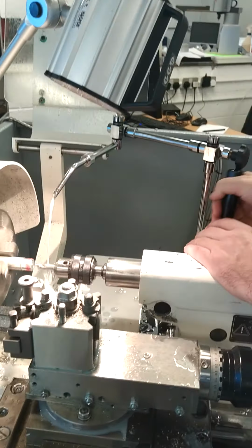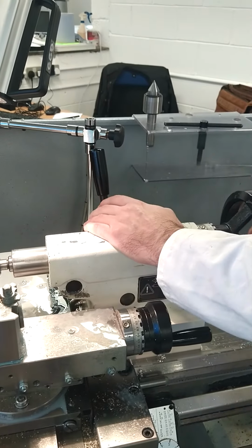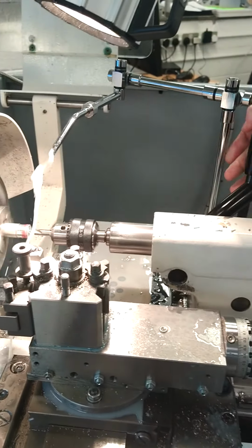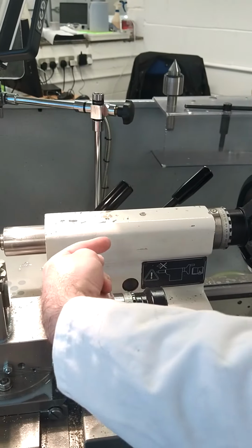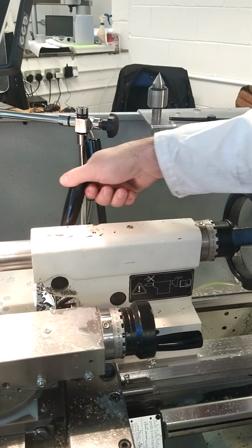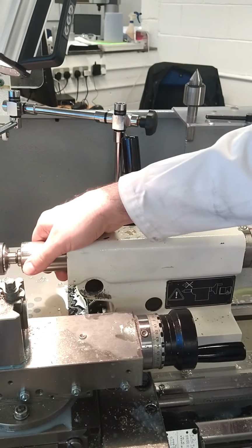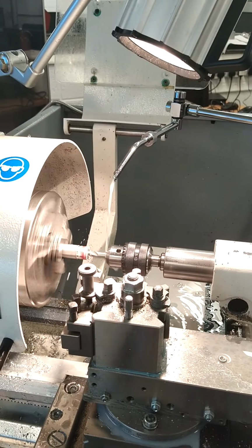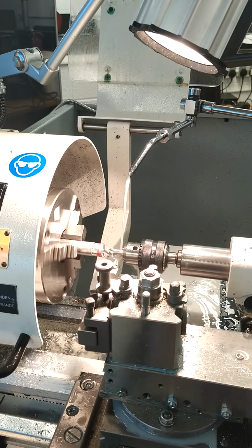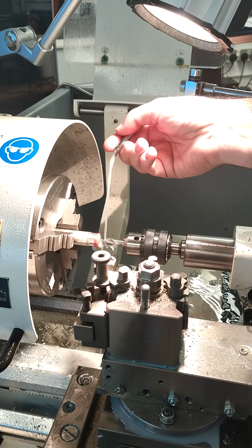So to make sure now is we have the lock on for our tailstock, and you're drilling forward. If you don't have the lock on, what happens is when you drill forward, the tailstock will move back. So ensure the lock is pressed on, and leave this quill lock off because that's stopping it from drilling. And you're drilling in so you create that kind of a cone shape on your part.